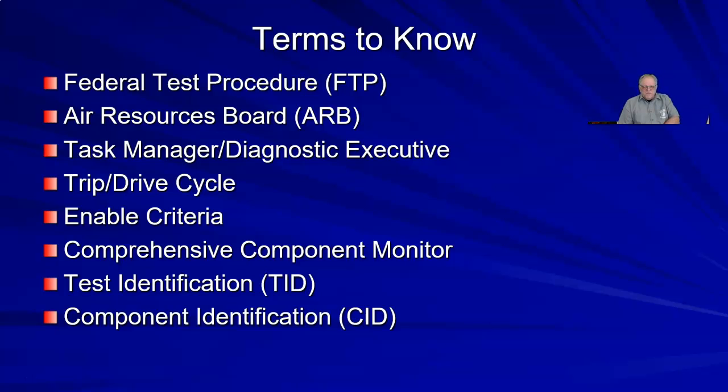Comprehensive Component Monitor is the task manager testing every sensor, every system on the vehicle that can affect emissions. When we get to looking at mode 6, and this will be on one of the later videos, there is a TID for test identification and CID component identification.